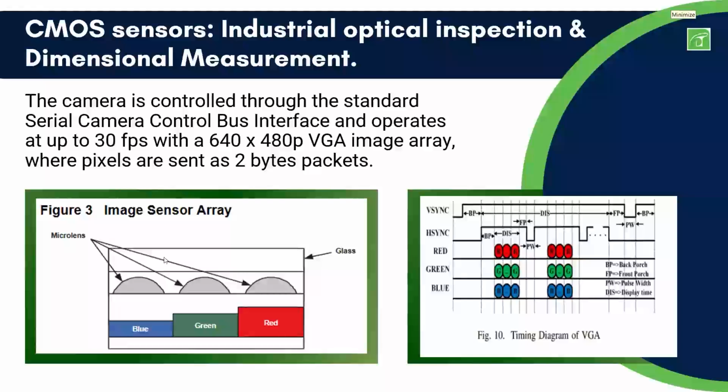So once this camera module has completely captured and is generating all those red, green, and blue components, you are converting them and writing a timing diagram in your RTL where you latch the red, green, and blue components on particular conditions. You may see that this BP, display, and FP are the back porch, the displaying part, and the front porch of your display signal.